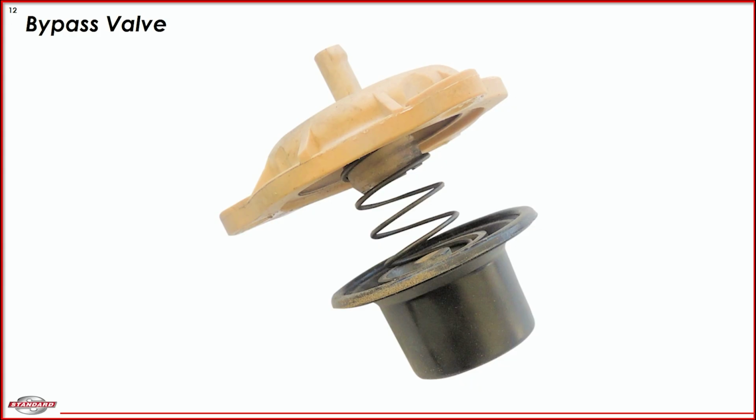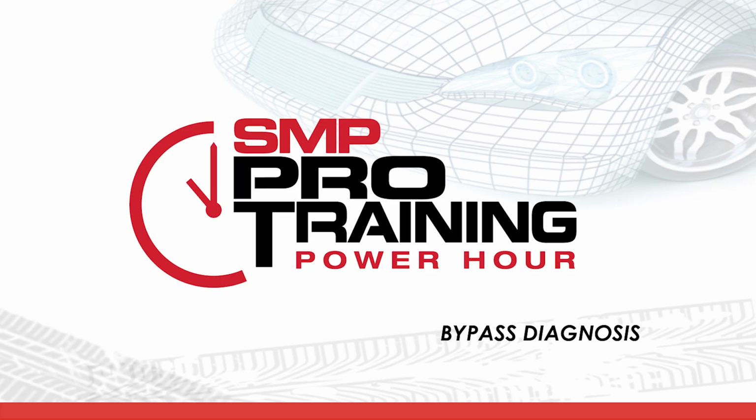Now, at the desired time, the PCM will apply vacuum to that diaphragm by energizing the bypass solenoid. And this is going to cause the plunger to lift and allow that passage to open so that the boost pressure is dumped. All right, so there's our brief description of how the bypass valve system works as a whole.